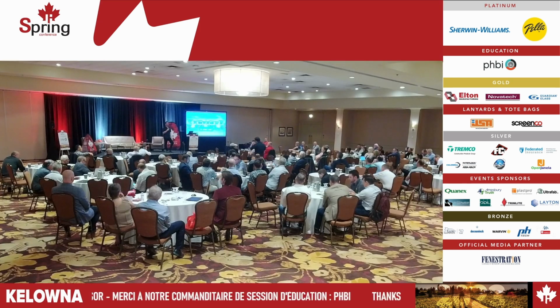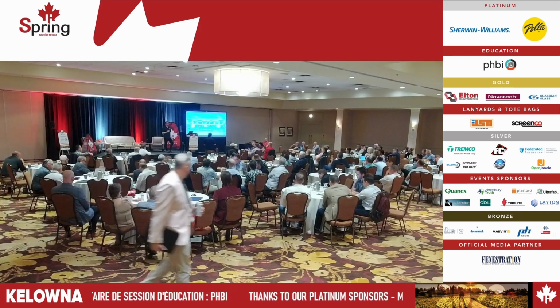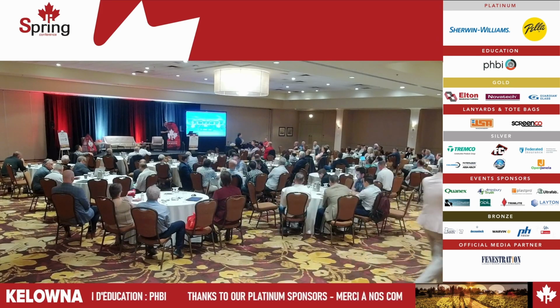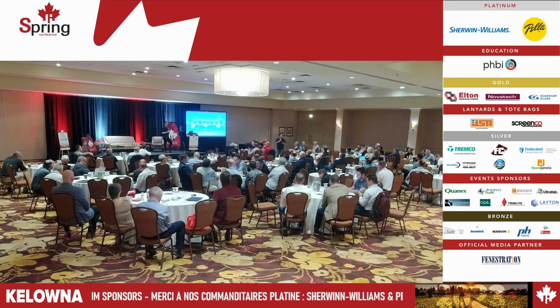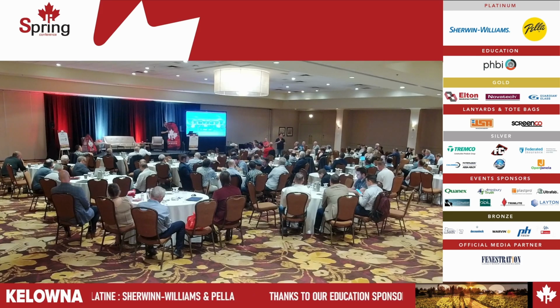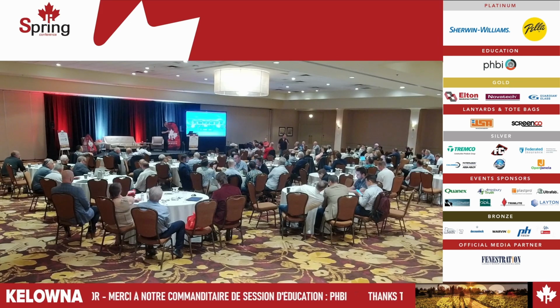Most of the manufacturers in BC are pretty familiar with the step code, and something that I certainly found when I was dealing with it was that your windows became a much better cost option. When you get into high performance windows, it can have such a much bigger impact on the performance of the home than a thicker wall or more insulation in the ceiling. And we found that pitching the cost for a triple glaze system or a high performance system actually became a much better cost benefit to the builder. So something to think about when you get into these home performance, home as a system scenarios with step codes and tiered codes, which are coming your way if you're not here in BC.